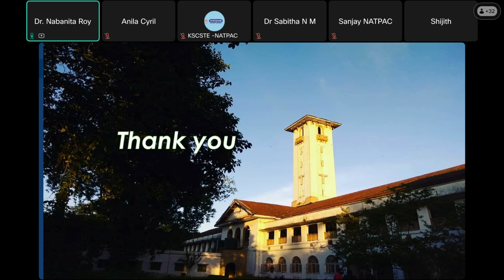No, temperature was not in the scope of my study. And for environment, like rainfall, we have collected the data during the rainy season also, in wet condition, with a 1 mm film thickness. So that adverse condition of the pavement when it is wet, we have taken care of. But we only collected wet skid resistance data. We did not collect dry pavement skid resistance data, and I did not take the variation.